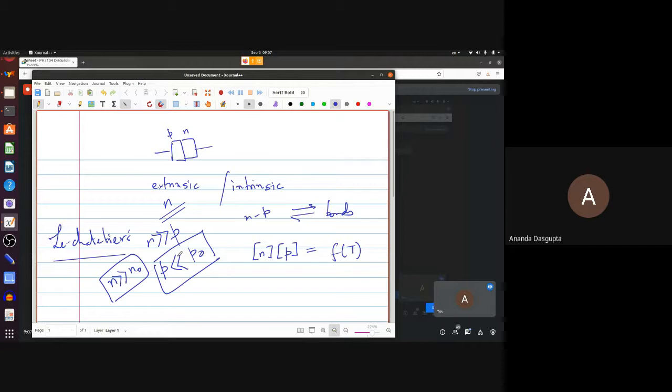But as temperature goes up, what happens? This intrinsic creation, which happens even in extrinsic semiconductors but is typically suppressed, becomes much larger, because the more temperature you have, a larger fraction of the objects will have enough energy to overcome the so-called activation barrier and break the bond. So basically, there's an exponential increase in the number of these thermal electrons and holes.